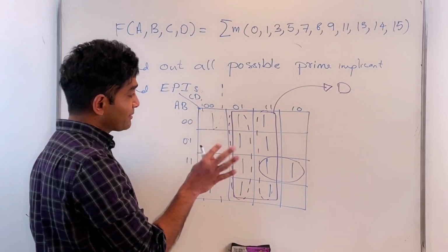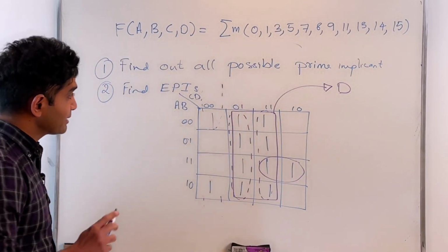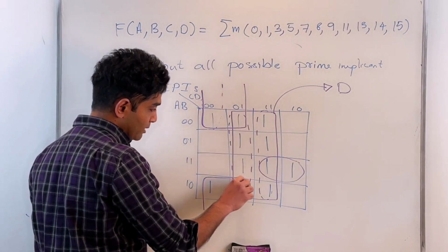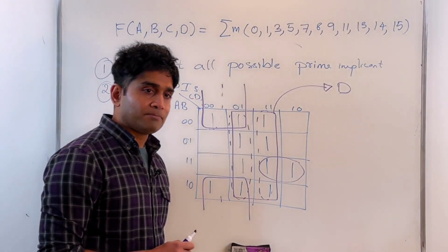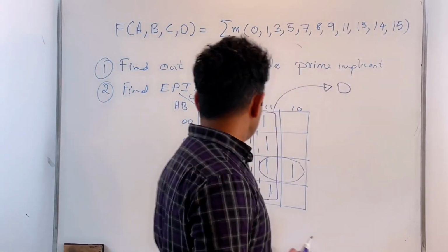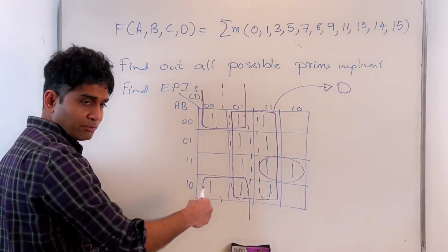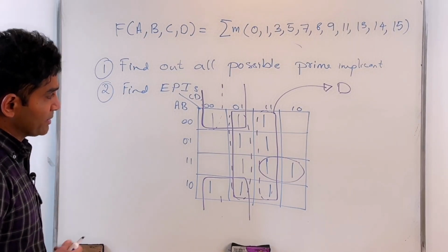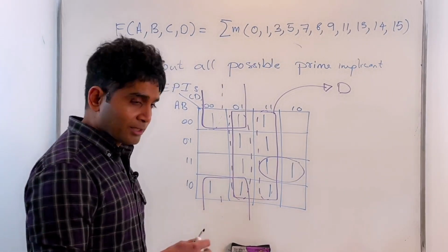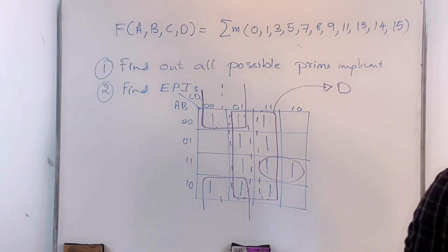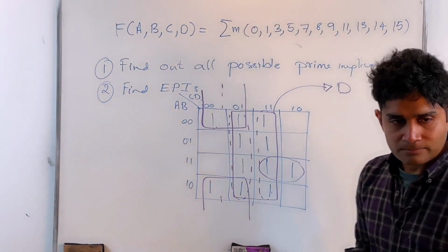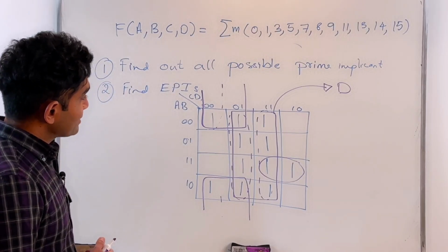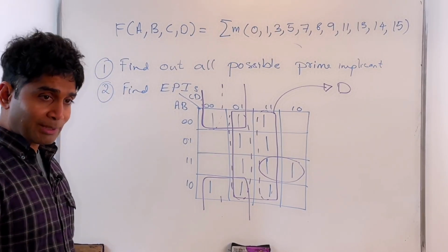Okay, so now hopefully that is clear. So that's going to be a prime implicant. For this particular combination, combining these 4 adjacent cells would give me the prime implicant in this case. So this would be the prime implicant, not individual combinations. Now, what can you comment about these prime implicants in terms of, are they essential? Do you see any non-essential prime implicants and so on? In this example, I see that all of the prime implicants are essential prime implicants, right?